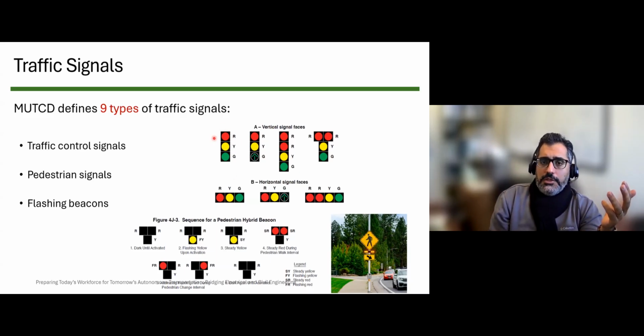It could be a signal like this. We have red, yellow, and green, only to allow pedestrians to move, or it could be something like flashing beacons or even alternating yellow lights. If you have pedestrian hybrid beacons, it is usually not active. When it is not active, it is similar to having green. So the default on the street is for vehicles to go.